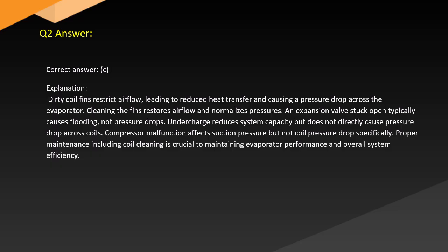An expansion valve stuck open typically causes flooding, not pressure drops. Undercharge reduces system capacity but does not directly cause pressure drop across coils. Compressor malfunction affects suction pressure but not coil pressure drop specifically. Proper maintenance, including coil cleaning, is crucial to maintaining evaporator performance and overall system efficiency.